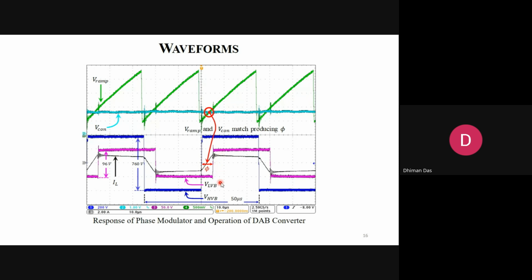Now if I oscillate this signal, this phi will oscillate and this current peak will also oscillate, with a small value. This is called the perturbation. In mathematics, we do the small signal perturbation when we break the component x into x plus small x bar or tilde. The similar thing is done in the hardware.